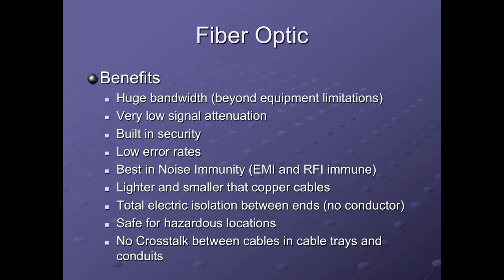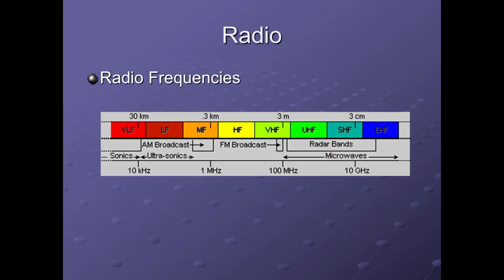Protection networks are using fiber optic networks a lot too, because they'll use a fiber optic cable to detect arc flash. When they have an arc flash, the light from the arc flash travels down the fiber optic cable, and it can trip that protection device in a much faster trip time than something like an electrical detection or 4 to 20.